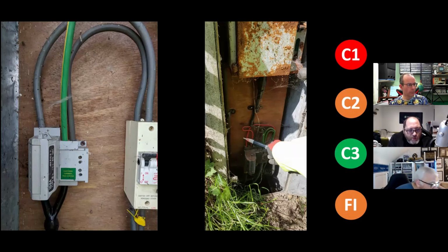Is that holes drilled on the side there off the cutout? On that Series 7, it looks like it's been chewed on. They're not very regular, are they? Somebody's attempted to drill holes in there. On the right-hand side, by the way, that's just another lighting feeder pillar, with single core conductors coming out of the cutout, and the volt stick to prove they're still energized. But let's stick with the one on the left, because it's DNO intakes we're coding.